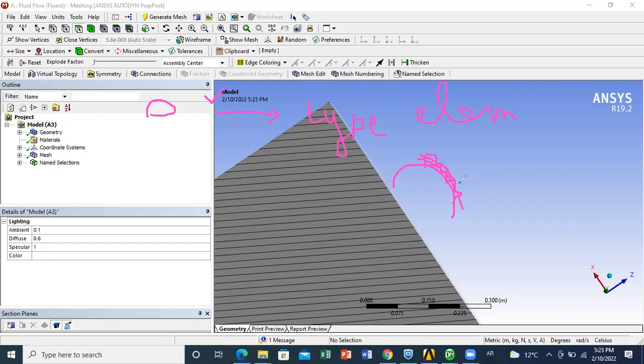By layering the zone near the curve, the wall or the curved part, we can deal with smaller elements, and we can trap this zone in a better way. These are some of the strategies that are used. Again, I detailed all of these strategies in recorded videos. Just now, I want to give you an overview of the meshing procedure.